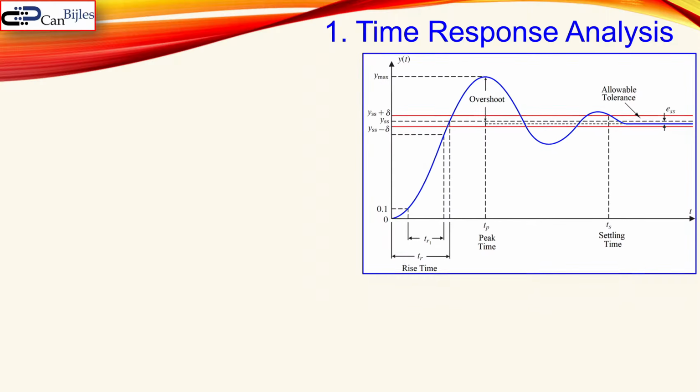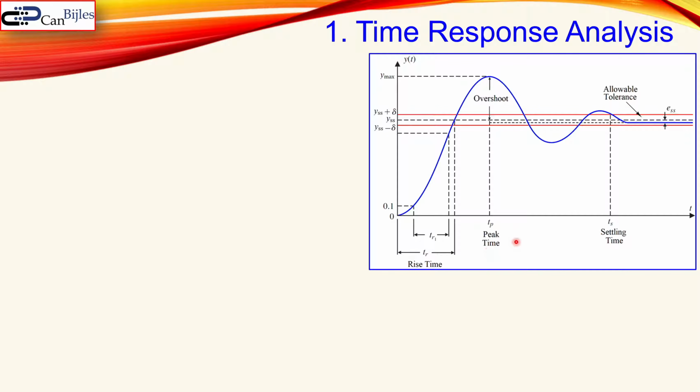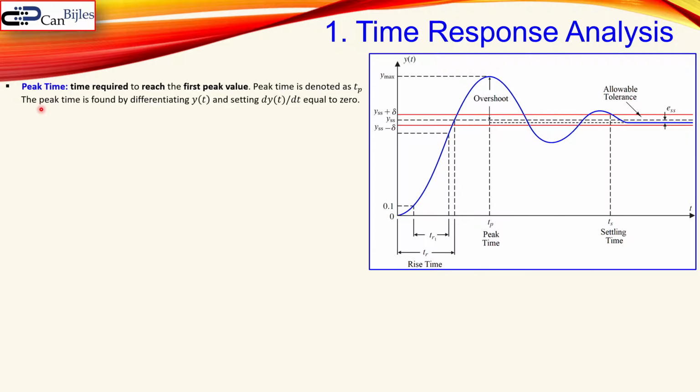Okay, let's see what we can also discuss about the parameters here, because we see the peak time here. What is a peak time? The peak time is the time you need to reach the first maximum peak of your output response. That can also be determined by differentiating the expression for our signal, y(t), and equating that to 0. So you find the moment where you have the peak. And that is given by this formula. Again, you see here the parameters we have discussed before. You see here omega d, which is the damped radian frequency. So it's actually a pretty simple formula.